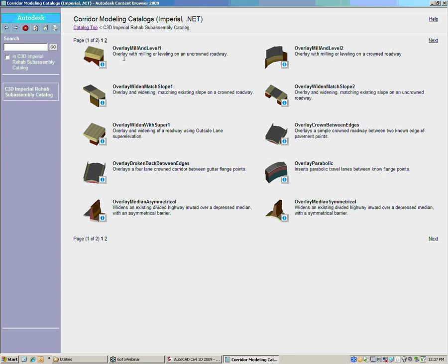If you're just doing a simple overlay where you're not adjusting any road slopes, that whole leveling course bit that we went through with the 3 profiles can be skipped altogether, and you just use this mill overlay leveling 2, and it does your overlay for you, keeps a minimum depth, does a mill if you need it. You have to read the help on here. But this does a bunch of calculations for you, but it doesn't allow you to set a minimum slope. That's why we have to use the 3 profile method. But there's a bunch of stuff in here.